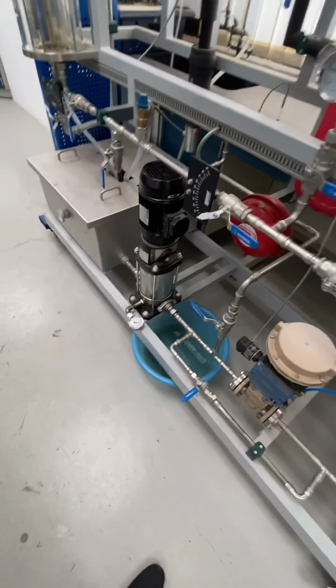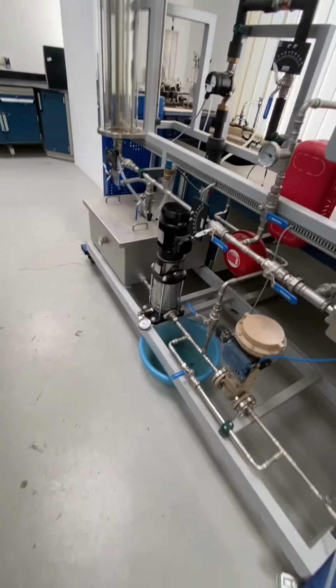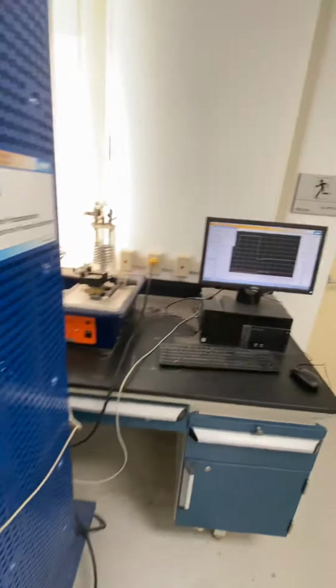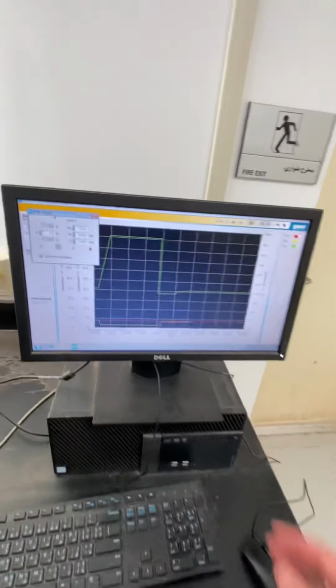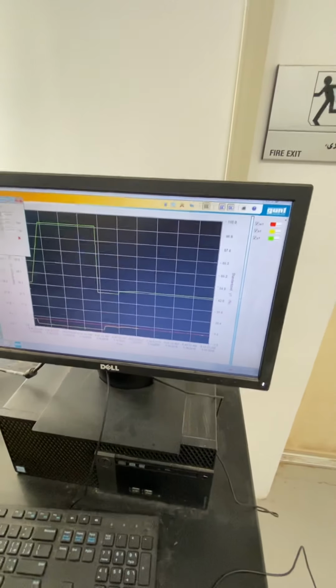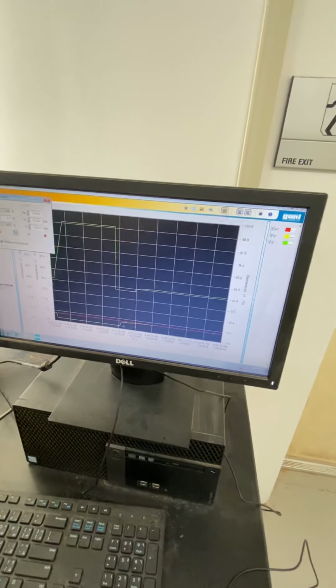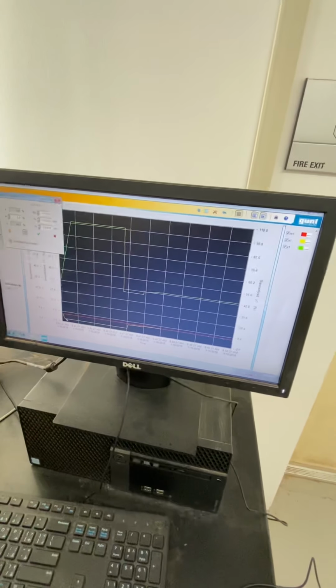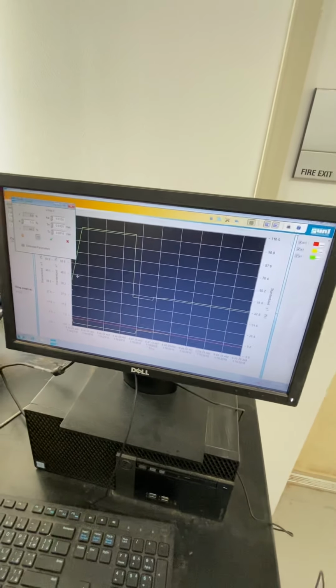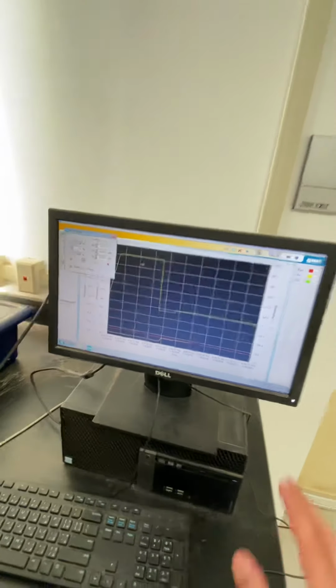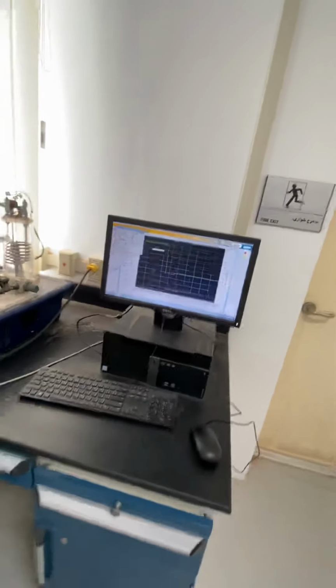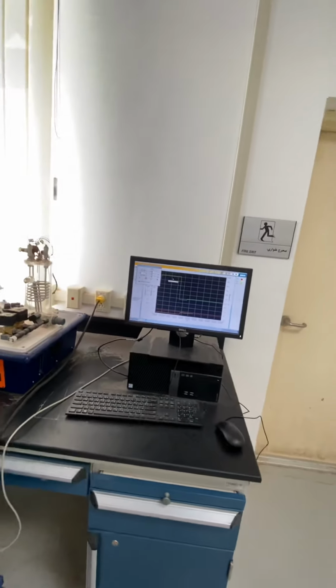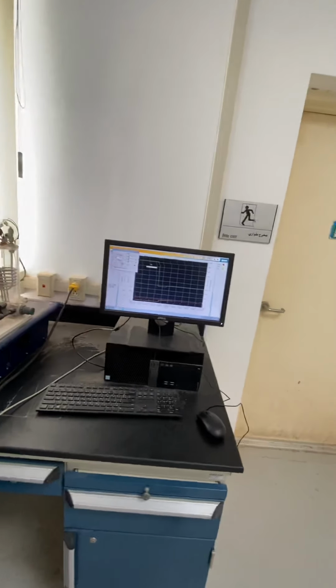Okay, and if that happens, guys, you will see that the process value will drop below the set point, and if it drops below the set point like here, you will see, guys, that this is a negative error, and as a result of that we will notice a slight increment in the controller output.